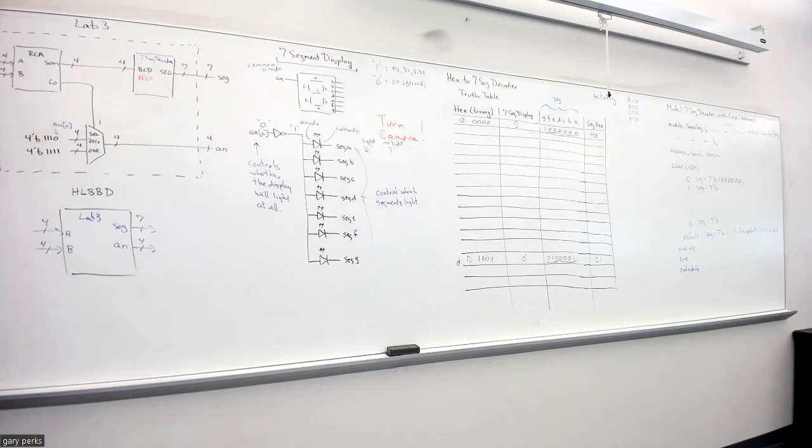Okay. Let's say we have an addition that gives us a carry out equal to 1. Now the select is a 1. So now what's going to happen at the mux? What happens here? What's the output of the mux going to equal if the select is a 1? Right, it's going to equal the data that's on the 1 input, which is all 1s.